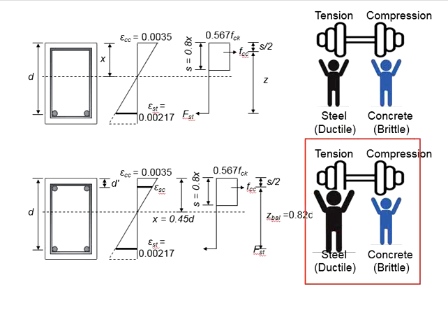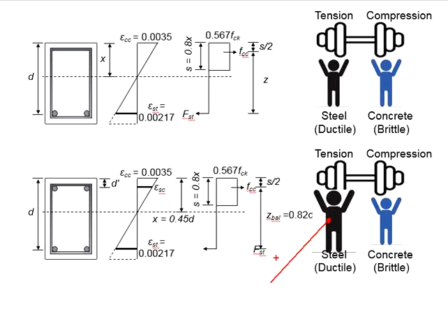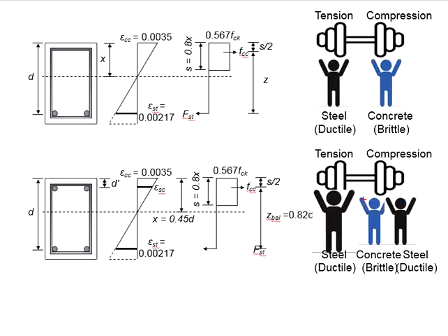Under such circumstances, there is no chance that this person will fail first when the member is overloaded. In order to prevent this, the concrete will require a helper taking the compressive stress. If one person cannot outperform the other, you have two persons to compete against the steel here. This will be the compressive steel, which is this.